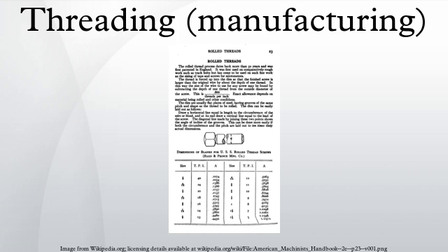Single point threading, also colloquially called single pointing, is an operation that uses a single point tool to produce a thread form on a cylinder or cone. The tool moves linearly while the precise rotation of the workpiece determines the lead of the thread. The process can be done to create external or internal threads. In external thread cutting, the piece can either be held in a chuck or mounted between two centers. With internal thread cutting, the piece is held in a chuck. The tool moves across the piece linearly, taking chips off the workpiece with each pass. Usually 5 to 7 light cuts create the correct depth of the thread.